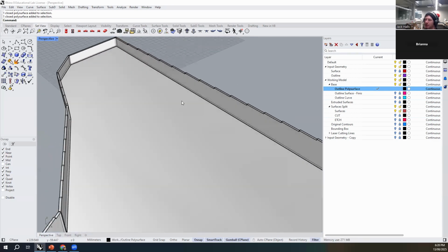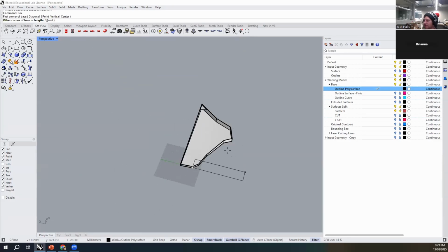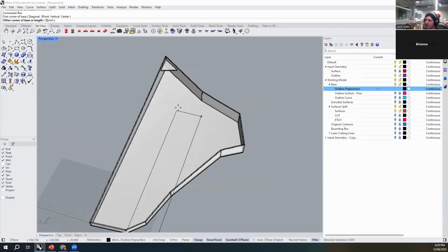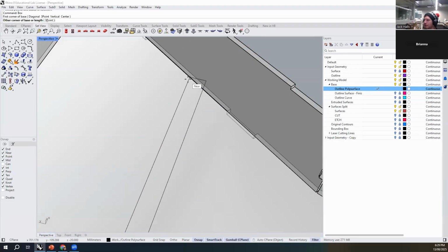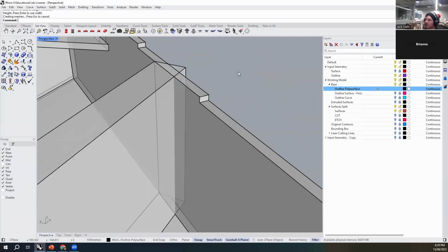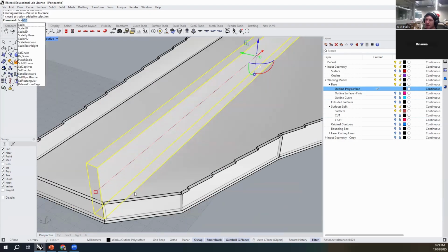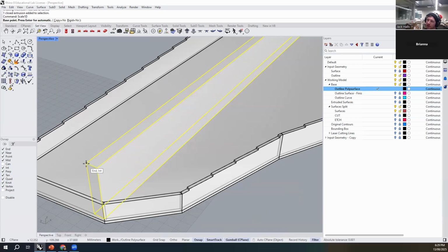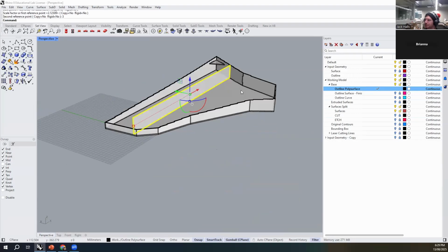So in order to do that, once again, I'm going to use that box command. I'm going to select a point over here arbitrarily. There's no science here. It's just sort of finding the middle of the space where you think a support might work and dragging out a new box. I'm just going to drag this out randomly, and I'm going to resize it so it can get way too big. Okay. I'm just going to use scale 1D, and I'm going to resize this to its 3mm dimension.